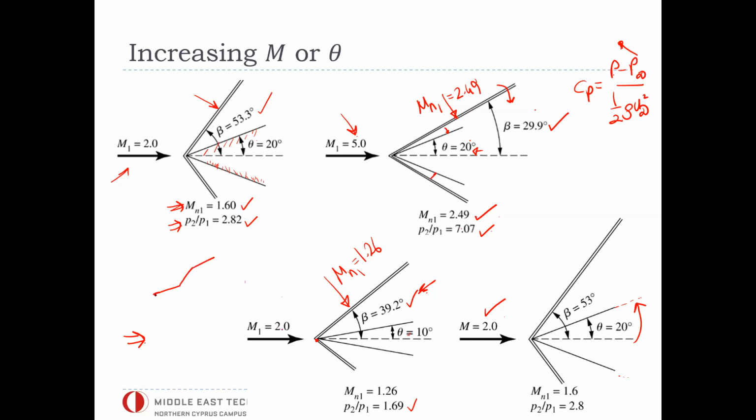Instead of making a surface flat, you have to give angles to reflect electromagnetic waves to different directions, so that you will reduce visibility on the radar. This was first tried in the F-117. That was one of the first fighter aircraft that used this, and I don't know if you remember its shape, but it's all triangles all over it. It did have radar problems, but it was basically mostly flying subsonically.